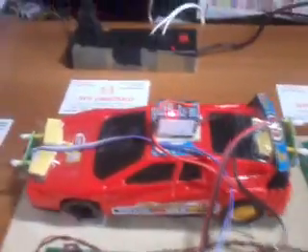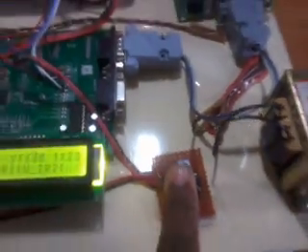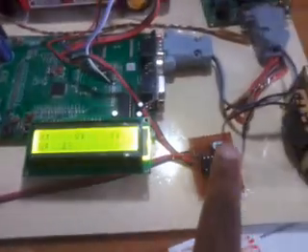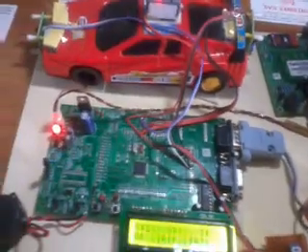So here we are using the car. The car consists of IR1 and IR2. We could connect the MQ2 gas sensor on it, but it would be complicated, so I connected it separately. Here I used one LM324 operational amplifier to amplify the signal of the MQ2 gas sensor, and it is given to P1.20. So first of all, I'll start the working.